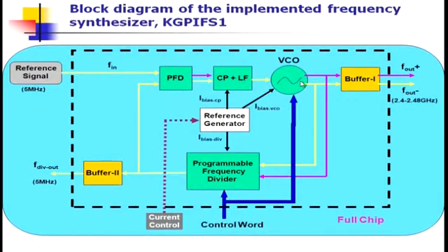and the VCO is now being fed to the programmable divider, and this programmable divider is controlled by a 6-bit word, and that also goes to the VCO to control the VCO. So, say 4-bit, 2-bit, like that, 4-bit you will go for the VCO switched capacitor architecture, and 2-bit for the programmable divider, depending upon how you make your word count at the digital logic array. And then you remember that after that we feed it to the PFD after its division. Suppose 2.4 gigahertz is the free running frequency of the oscillator, and the divider at this moment is 480, then 5 megahertz will come and it will compare with this reference frequency.